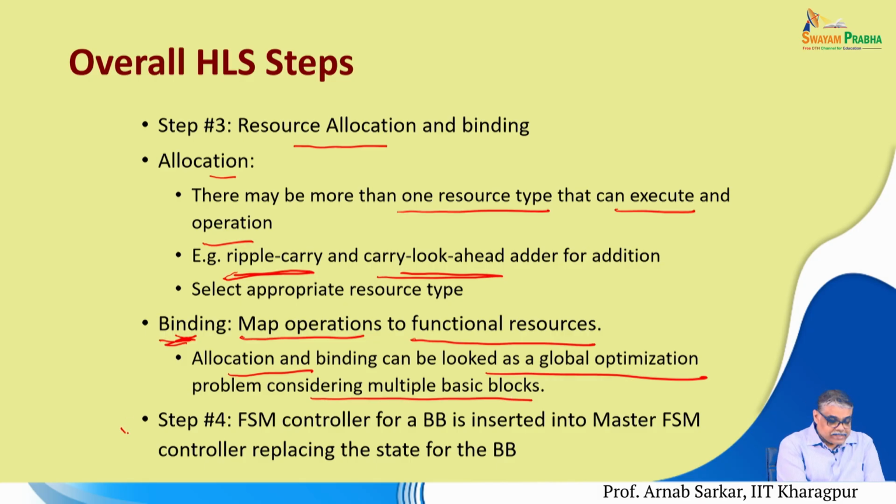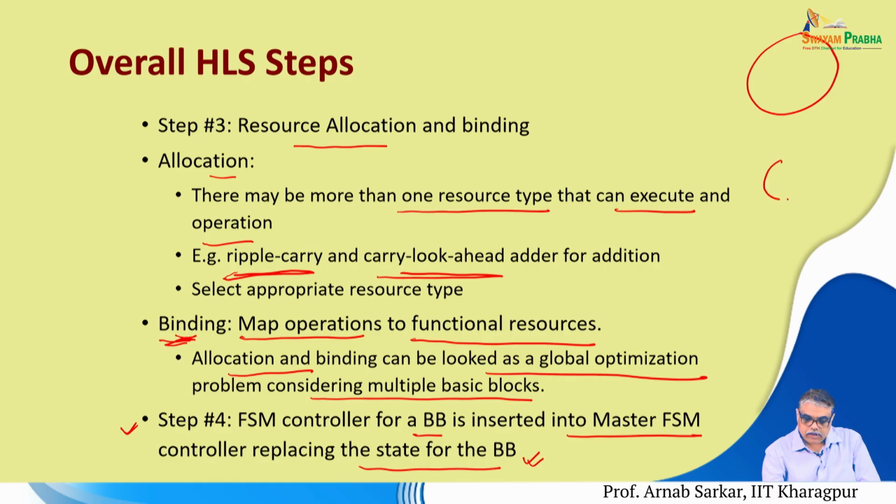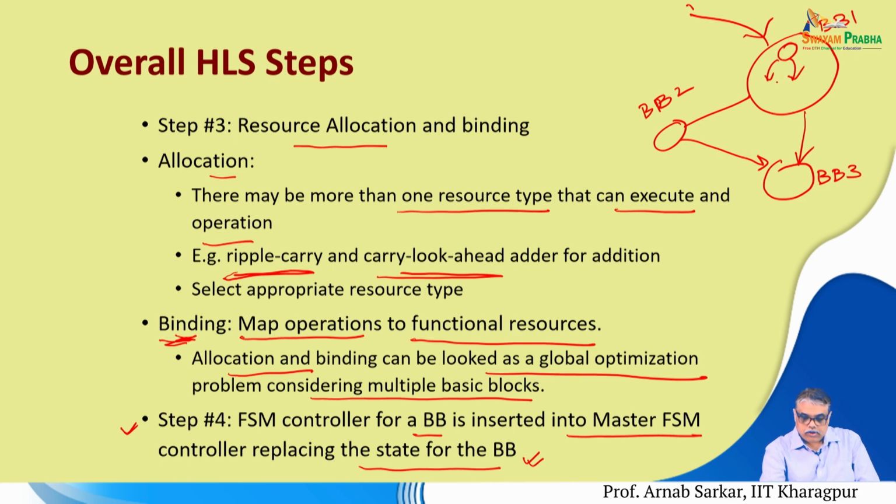And then, lastly, in step 4, the FSM controller for a basic block is inserted into the master FSM controller, replacing the state of the basic block. Let us say this is the master controller, this one was basic block 1, this was basic block 2 and this was basic block 3, and now we replace the node for basic block 1 with the controller for basic block 1.